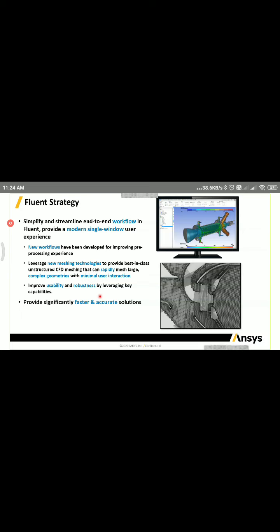If the flow is going fast, whether you have a sufficient number of elements or nodes to capture that physics, whether you have the number of prism layers to capture the boundary layer phenomenon, you have all, and so on. So there are different things that need to be decided before you go for any application or any simulation.